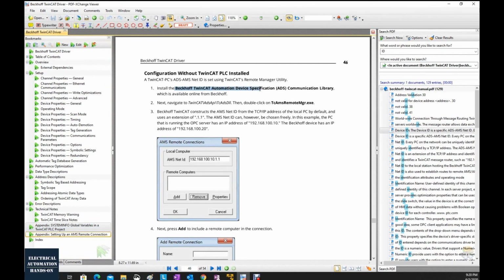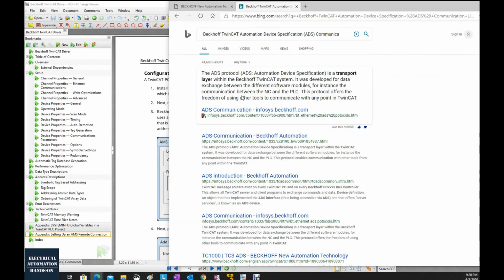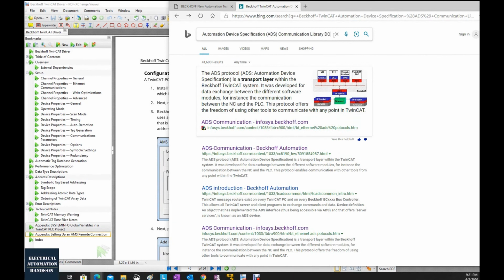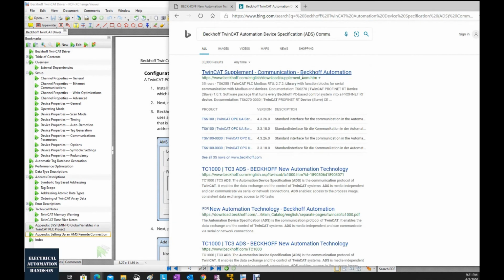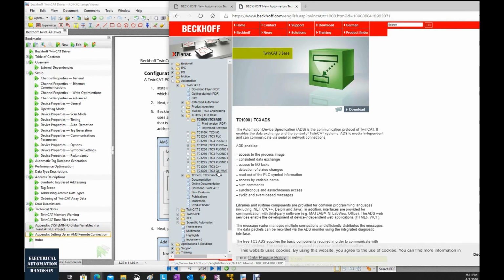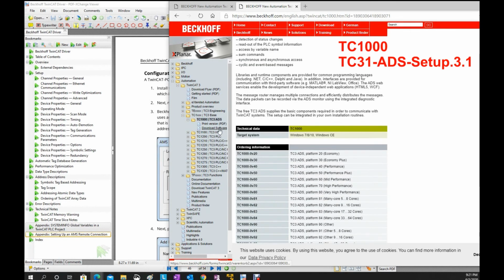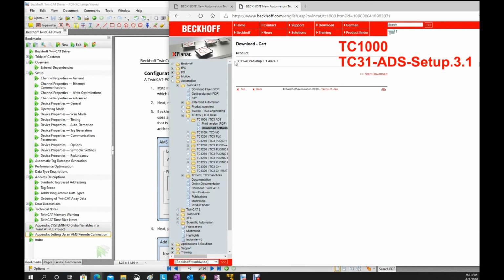So I think this video is valuable for you to look at how we can download this ADS file, how we can build up this router to build up the communication with one remote CX controller or Beckhoff controller. Alright, from Google, let's search TwinCAT ADS. Double click. Click this TC1000 ADS. We will jump to this page, TC1000 ADS. Here's this download software. We need to download this TC31 ADS setup 3.1. This is the same version as your TwinCAT3 software.